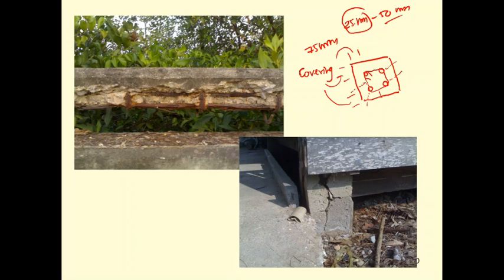When steel rusts, the steel increases in volume, and then the covering is going to get what's so-called spalling. This is called the spalling. Part of the concrete comes off its section, and then the reinforcement will have corrosion very quickly, and the structure is in danger of deterioration.